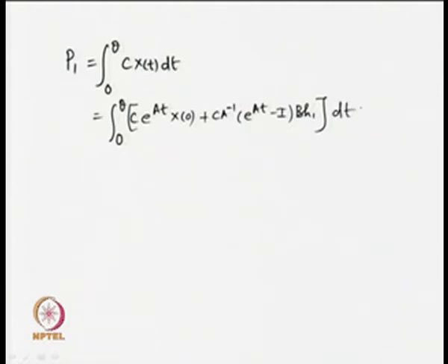So, what is this? The c has been multiplied with x(t), the state variables of the system, and we have to integrate it for the time range t spanning from 0 to theta. Now, when I start integrating this, I will find the expression c A inverse e^(at) with limits 0 to theta with the multiplier x(0). Again, for the second part, it will be c A to the power minus 2 e^(at) with the limits 0 to theta.